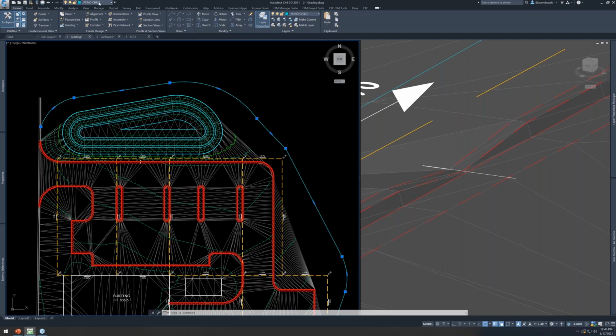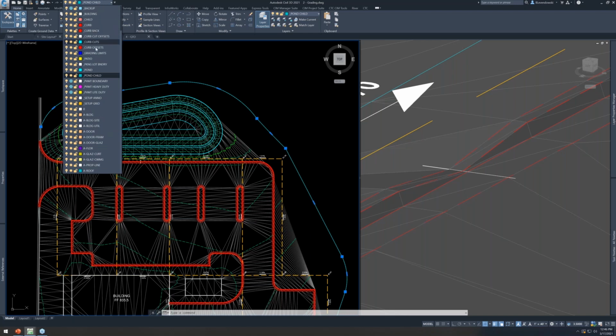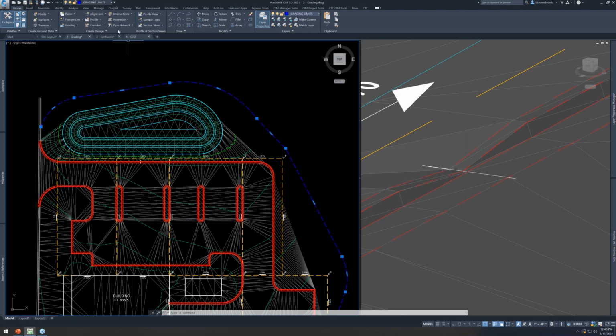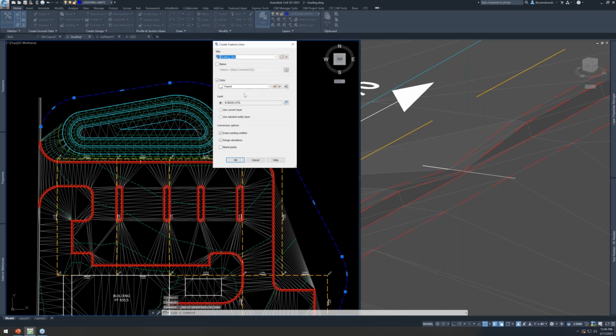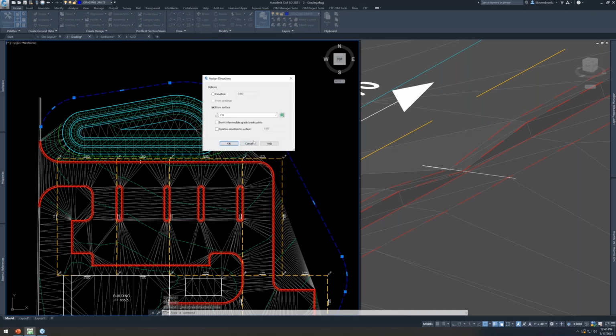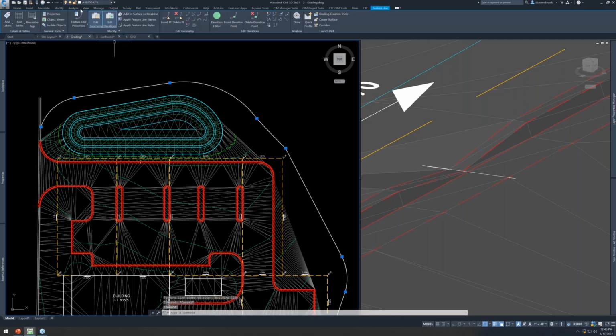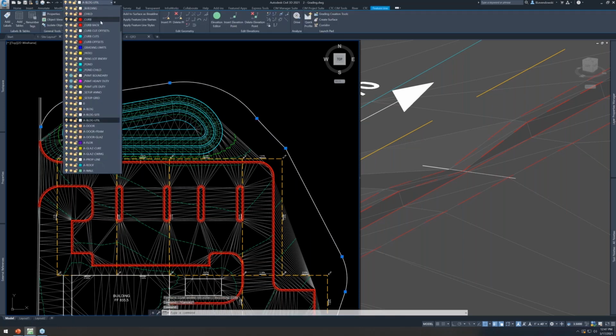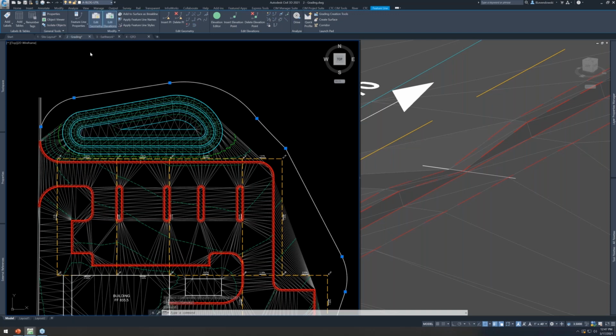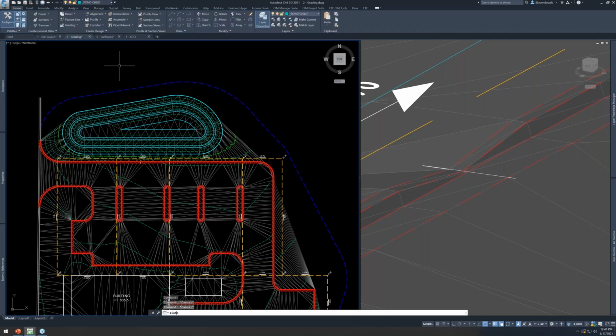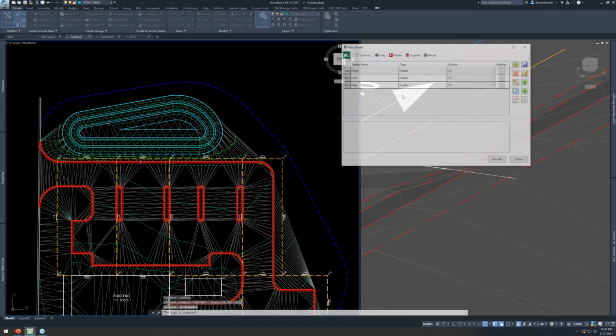So I'm going to go ahead and put this on a particular layer, grading limits. We're going to create a feature line from that. I'm going to assign some starting elevations of 834. I meant to keep that on the same layer. Let's go back there. Let's go in and create one other grading family.